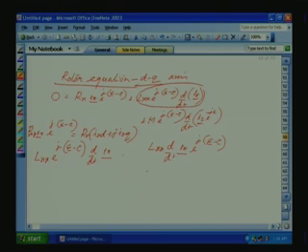This we can write as, first we differentiate the IR, the space vector. So, e raised to j (epsilon minus rho) into LRR into d by dt IR, then plus j (epsilon minus rho), that will be equal to j into omega r, the rotor speed. d epsilon by dt is equal to omega r.